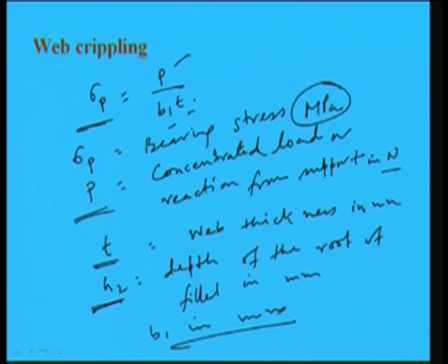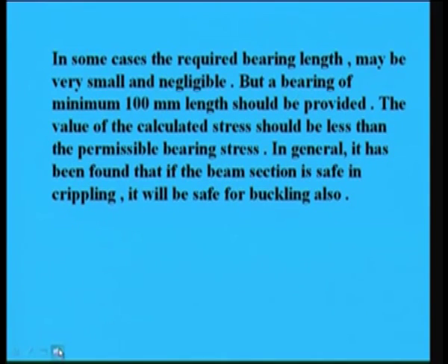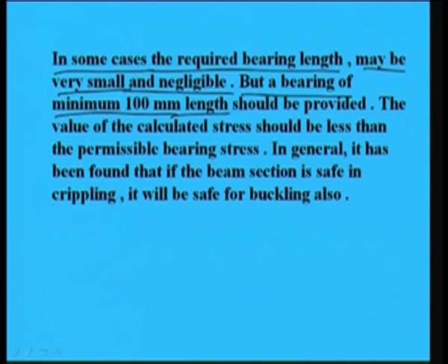Again, whatever bearing length we are calculating may be negligible or very small. Sometimes in some cases the required bearing length may be very small and negligible, but in this case a bearing of minimum 100 mm length should be provided. So, in any case a minimum of 100 mm length of bearing should be provided. The value of the calculated stress should be less than the permissible bearing stress. Permissible bearing stress we have shown.